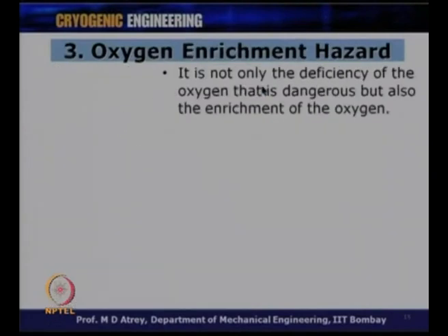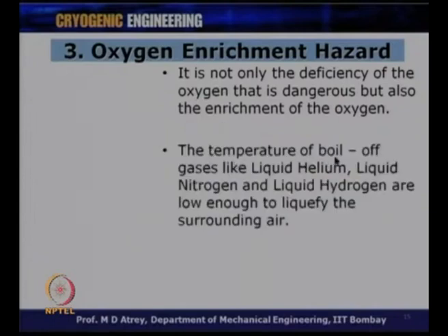The third is the oxygen enrichment hazard. We had talked about the oxygen deficiency hazard, and now we have the oxygen enrichment hazard. It is not only the deficiency of oxygen that is dangerous, but also the enrichment of oxygen. So, if on the other side oxygen has been enriched in the atmosphere, that also will cause problems. The temperature of boil off gases like liquid helium, liquid nitrogen and liquid hydrogen are low enough to liquefy the air. So, if you have pipes or surfaces which see these temperatures, of liquid helium, liquid nitrogen, liquid hydrogen, it can actually liquefy the air around it.